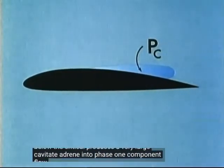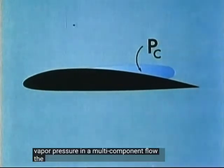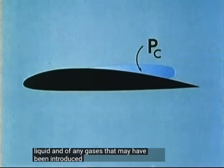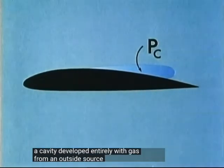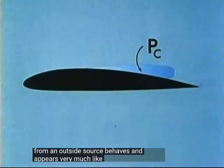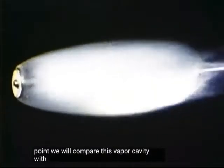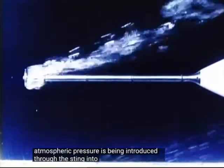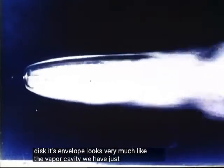In two-phase, one-component flow, the cavity pressure is just the vapor pressure. In a multi-component flow, the cavity pressure is the sum of the partial pressures of the vapor of the liquid and of any gases that may have been introduced into the cavity. In fact, a cavity developed entirely with gas from an outside source behaves and appears very much like a cavity formed by means of the vaporization process we have been discussing. To illustrate this point, we will compare this vapor cavity with an air-filled cavity. Air at near atmospheric pressure is being introduced through the sting into the wake of the disk. Its envelope looks very much like the vapor cavity we have just seen.